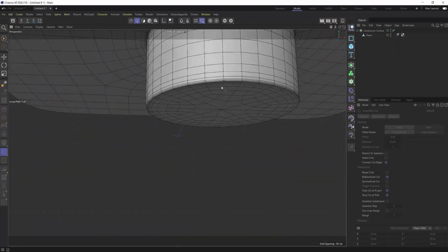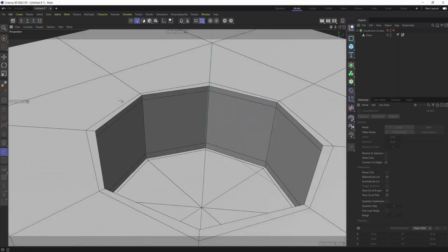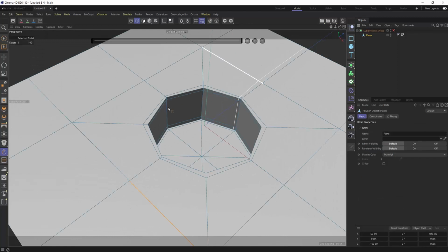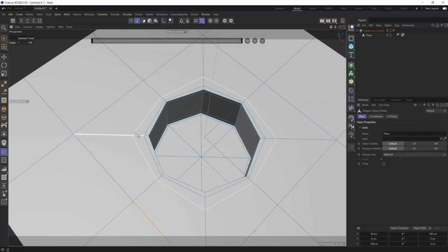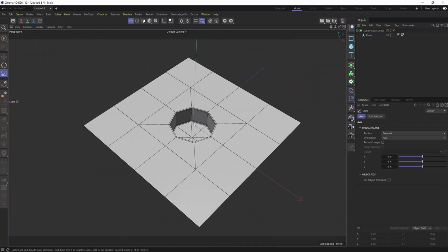And we're now defining the edges by the edge loop, and it's giving the corner and giving this object its proper characteristics. Now, when we did this edge, because the distance is different from one point to the next, you can see it's pulling these corner points out a little bit too far. A really simple thing we can do to fix that: if I just go in the point mode, my move tool, I can grab all the points that are pointed outwards a bit too far, select them, and then hit my scale tool, T, and just bring those in. Just like that. All right. And now we've got some nice uniform points here.